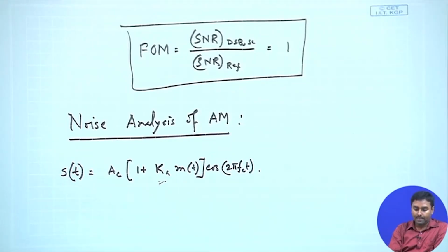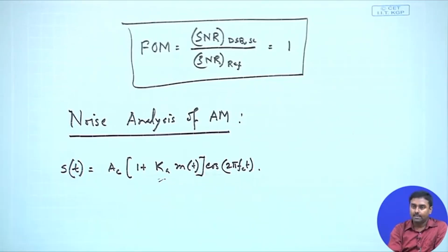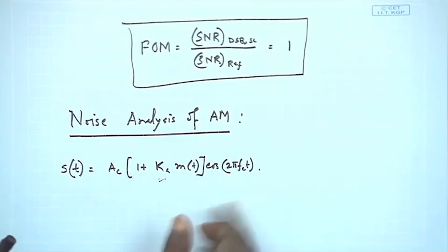Okay. So, basically what we do is nothing but we actually add a DC to the signal and then modulate, or do a DSB-SC, or otherwise in a way you can see it as the DSB-SC plus the carrier part. If you just multiply this, that should be the carrier part. So, the carrier has also been added over here. So, this is our modulation.